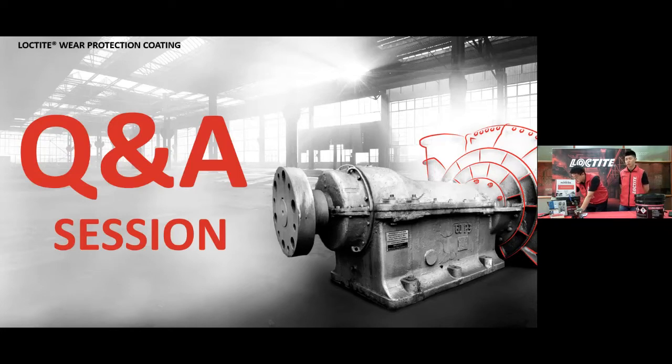If you are looking for a much smoother surface, I think there are three ways. First, don't mix a huge quantity of this wear compound. The larger the quantity you mix, the faster the curing, because the chemical reaction is exothermic, and an exothermic reaction generates heat and causes the curing to be much faster. So my first recommendation is to mix a smaller batch so that you can handle the product much more easily. Second, if you are looking for a smoother finish, you can top coat using Loctite PC7227, or what we know as Loctite brushable ceramic, so that you get a very nice smooth finish on top of your repair.